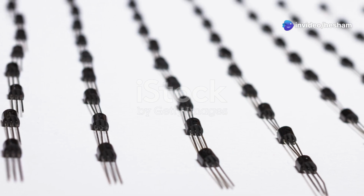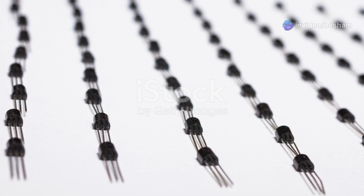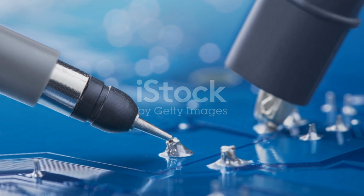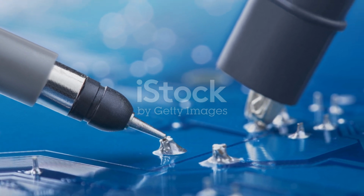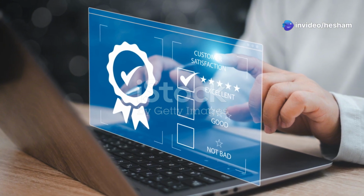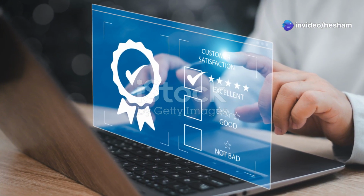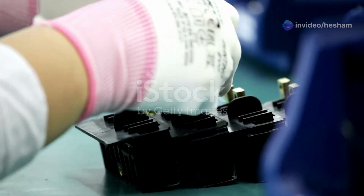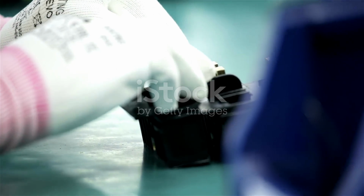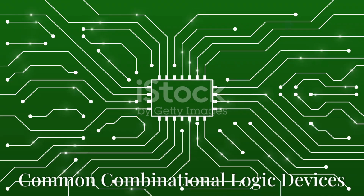Finally, you would use logic gates to implement the circuit based on your Boolean expressions. The last step is testing. You need to make sure your circuit works as expected for all possible input combinations. This involves applying different inputs and verifying that the output matches your truth table. Designing combinational logic circuits is a fascinating process that combines logic, mathematics, and electronics.